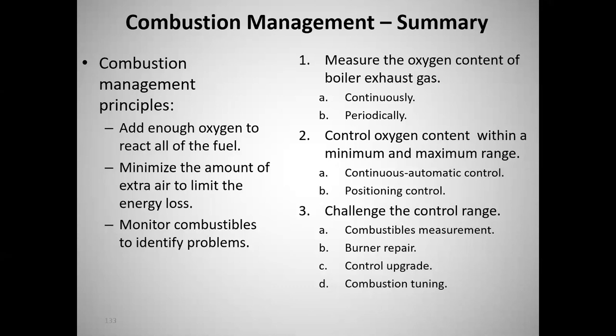Now, I will say the small handheld instruments are fine if you've got a duct coming out of your boiler that's this big or this big. If you go to a big boiler, you've got a 6-foot duct coming right out of the boiler carrying that flue gas. Well, if I've got a handheld instrument, I've got a wand about that long and I stick it in there. I get a reading, but how well does that reading indicate what's really going on across that whole duct? That's what you don't know.